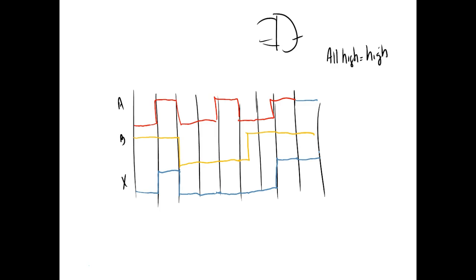No, the two diode gates we had next door. I can understand, I didn't put a sign in there. On diode gates, an AND gate is an AND gate, whether it's nothing but diodes or says all highs to get a high. Any OR gate says any high to get a high, right? You understand that? So there's no mirror like you were saying a while ago. Mirror means if I had all highs or all lows, and that's not true for these gates that we're dealing with now.